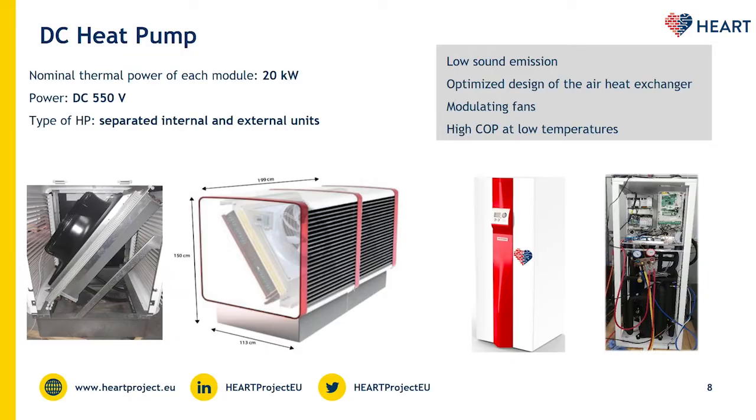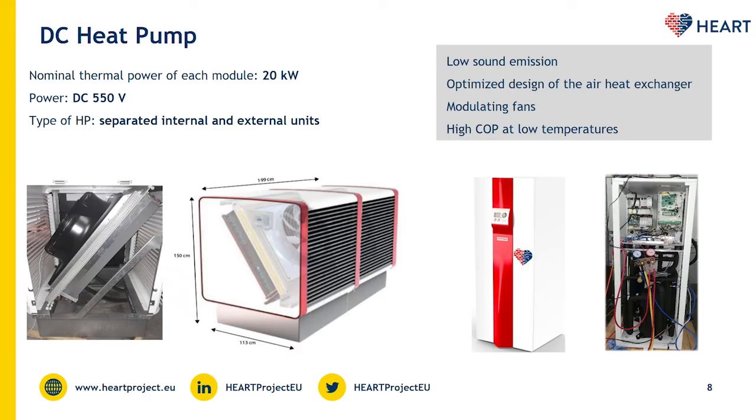The DC heat pump has instead a separated internal and external unit with a nominal thermal power of 20 kW. The outdoor unit has modulating fans and an optimized design to ensure a low sound emission. The heat pump ensures high efficiencies also at low air temperatures. As mentioned before, the power voltage is 550 volt.